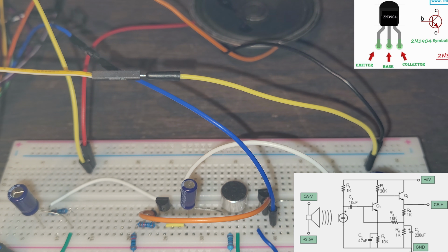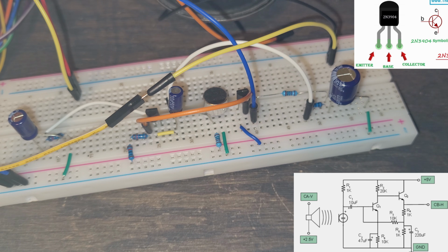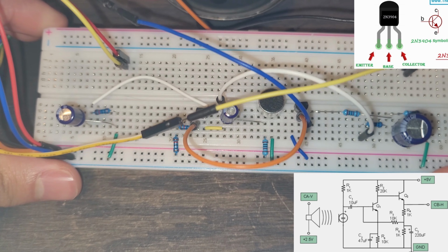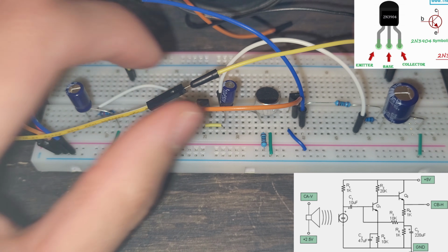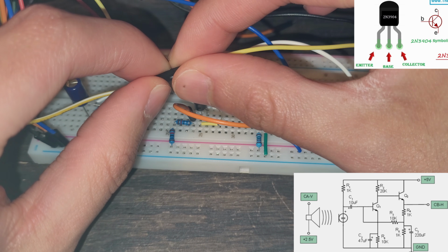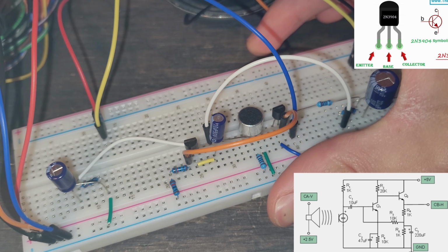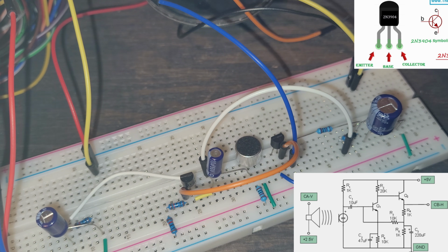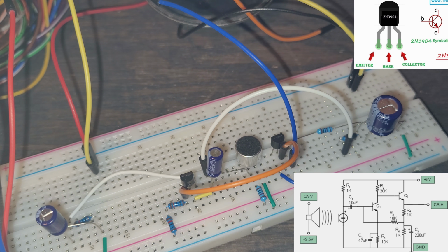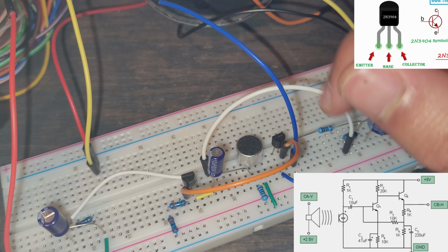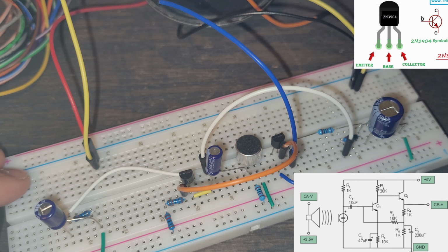So what we can do is look back at our supplies. And then we're going to stop the breadboard right here. If we need it, we can always come back to it. Everything looks correct in our circuit. However, there are a few things that I need to make note of. The first is that we have our overcurrent protection whenever we turn on just the power supplies, right? Not our WaveGen 1. So we know it has to be a problem with the way something is delivering power.